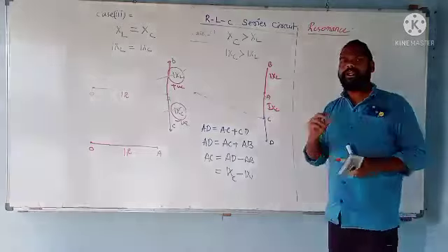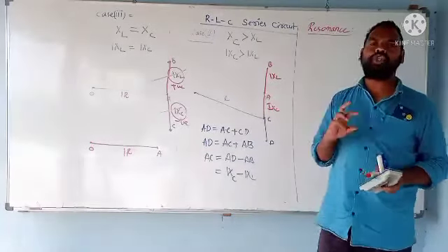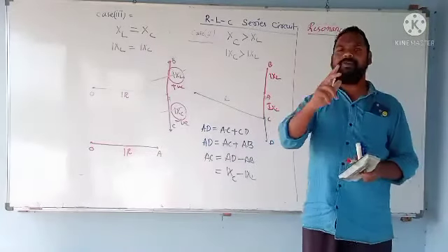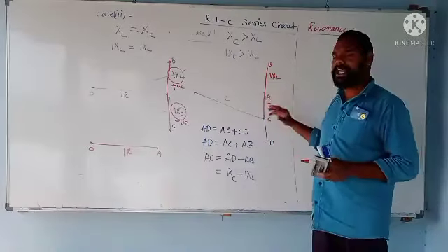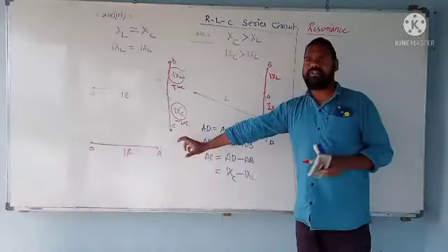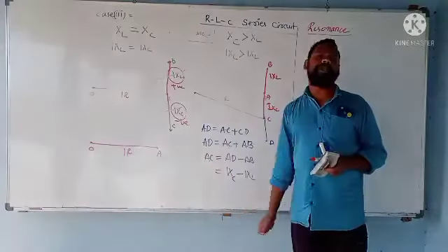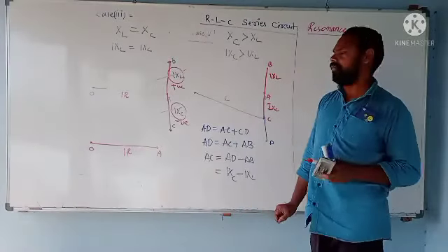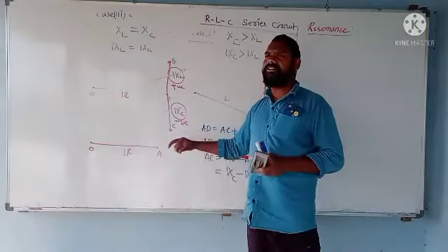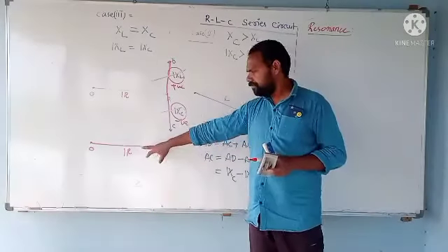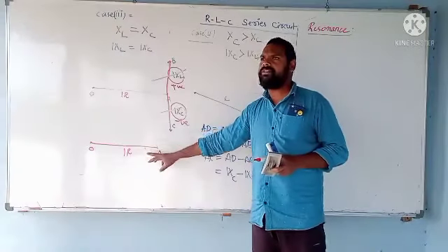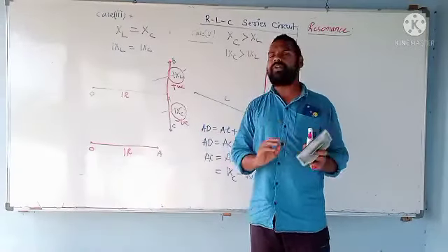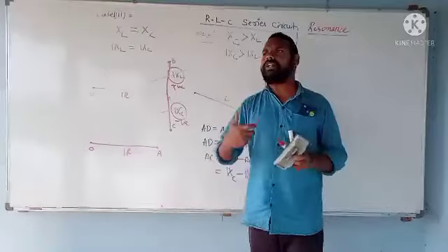In this way, the distribution companies, whoever sends the power to you, compensate the reactances like this, and it means the circuit actually behaves like a resistive network. Whenever it behaves like a resistive network, the current is always in phase with the voltage, and the angle between these two will be almost 0. So that is why the power factor will be improved.